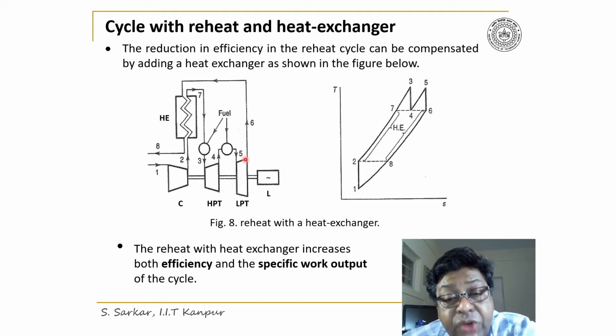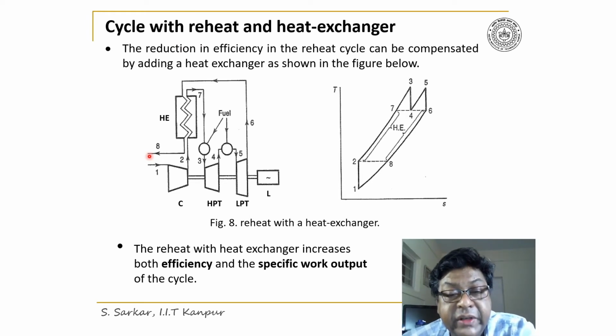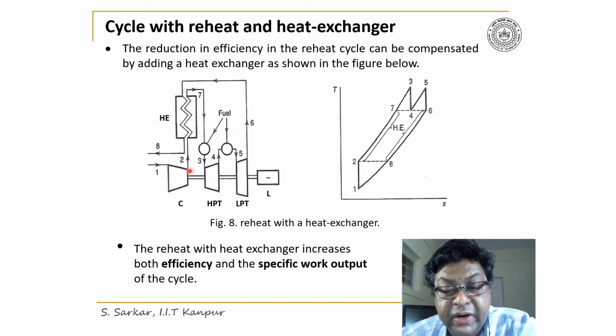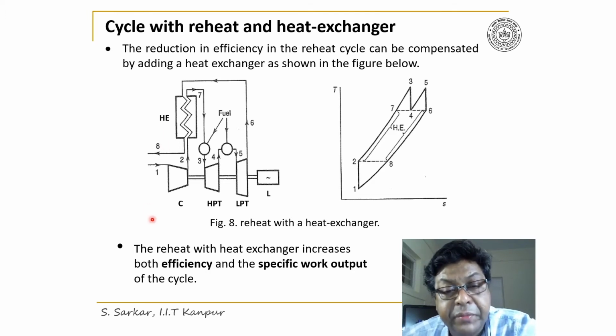Further, the exhaust from the LPT is now passing through the heat exchanger, and therefore it is utilizing the exhaust temperature, which is normally higher than the compressor outlet temperature. So, look here, a heat exchanger between the compressor and the LPT is also provided to utilize the energy.